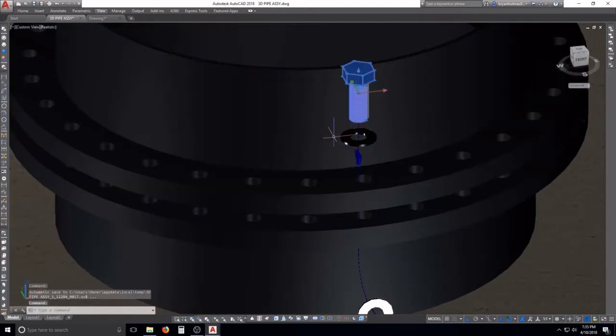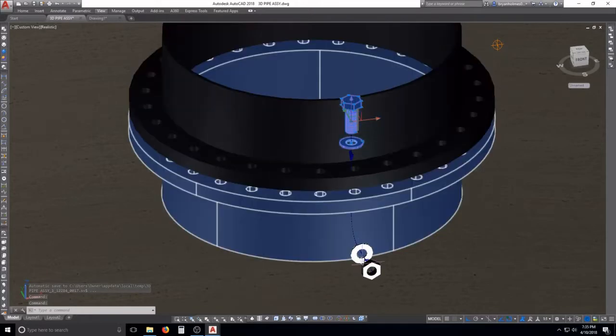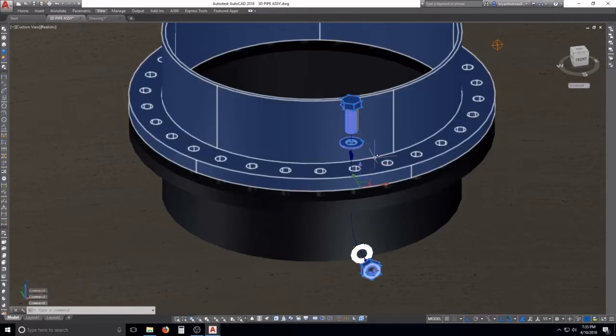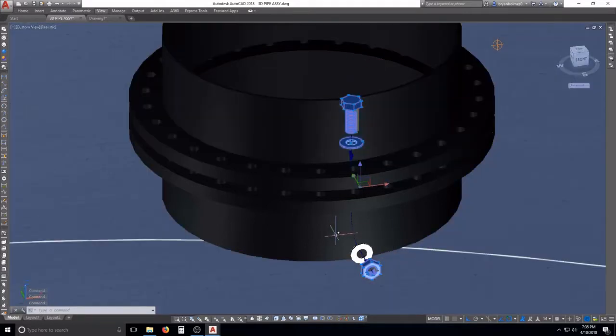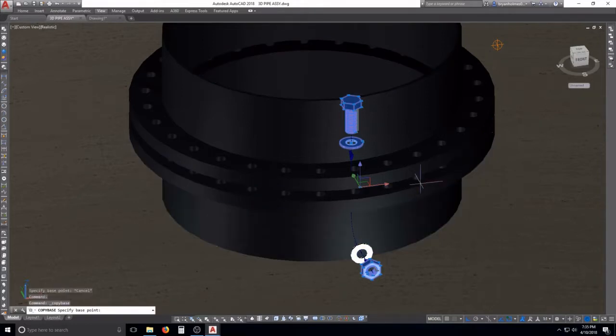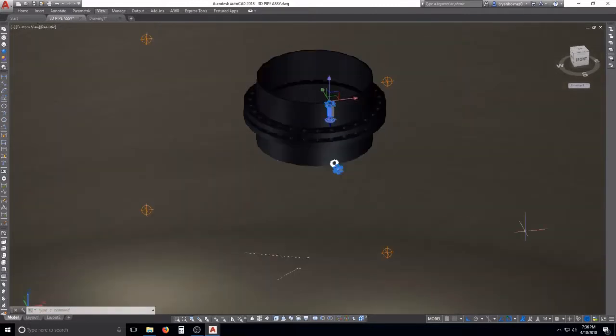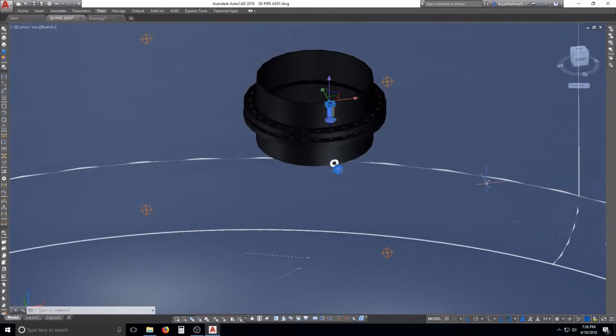So what we're going to do is copy from one drawing to another. I'm not going to copy that second washer. I am going to copy this though. You select your items from one drawing to another. If you want to copy, you can go Control C. Now, if you want to copy about a base point, do Control Shift C while you have them highlighted, and just click anywhere. That establishes an insertion point. That's where it's going to insert about. Because if you don't do that, it might have the pick point way over here, because it's going to pick it for you.